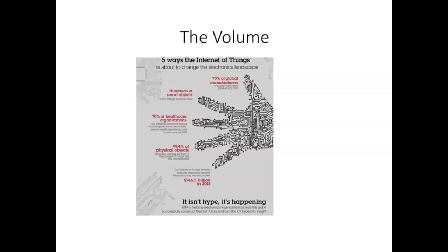When containment is broken, it's very hard to determine. Well, with the IoT technology and the ability to put sensors up to the cloud, it's very simple to put a pressure differential device into an area through a little hose that's sealed on the outside, with a device that is connected to the internet and will alert somebody when containment has been broken. The only way right now to know if containment has ever been broken is to get there and monitor it yourself in person.